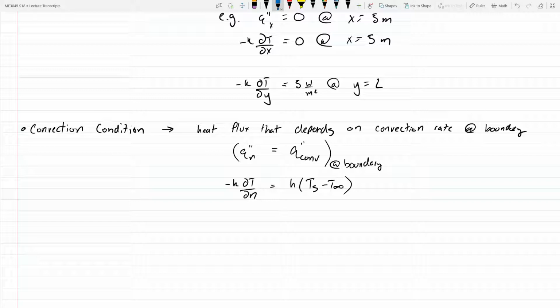So if we're talking about one-dimensional heat transfer, okay, if we're working just in our x coordinate, like that first version of the heat equation that we derived, our boundary conditions are just going to be on x. In that case, n would be replaced with the coordinate direction normal to the surface we're considering. The idea here is that the surface is an evolving temperature field, say the thing starts out at some temperature. You heat up a block of metal in your oven, and for some reason, you set it out to cool, like any good metal baker would.